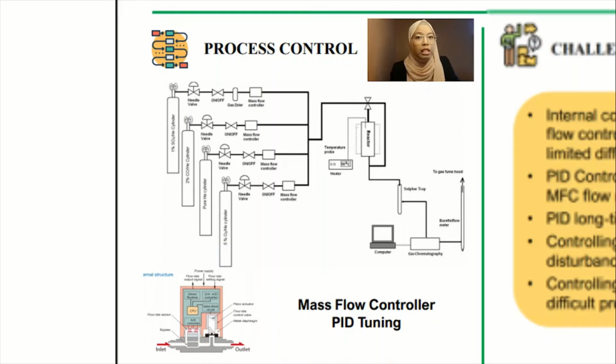and can form other sulfur oxides, which leads to water pollution. To avoid this happening, a treatment method for SO2 gas was introduced, which is called flue gas desulfurization (FGD). FGD is a treatment process for SO2 gas, in which the flue gas will be contacted with limestone slurry or lime. Then it will absorb the SO2 gas and become a white sludge of calcium salts. This end product can be safely disposed of. The schematic diagram here is the reactor system for SO2 reduction.